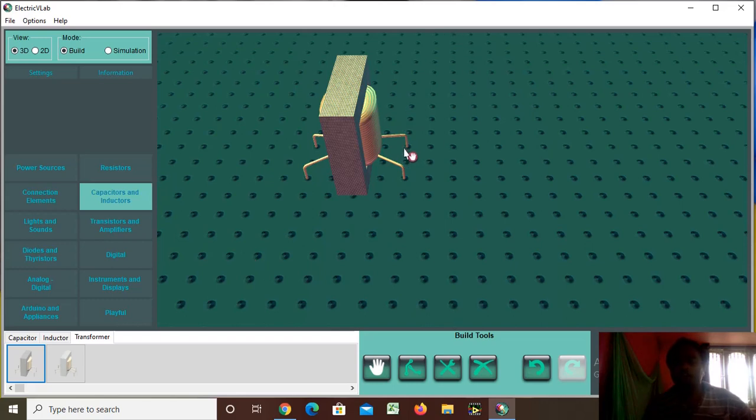Now here the diode is connected in series with respect to the secondary, and as well as the load. I just want to connect the load and the diode here. We will connect it later. Now I'll see how to put the turns ratio here. So what is the primary voltage? The primary voltage is 230. I just want to apply 230 volts.